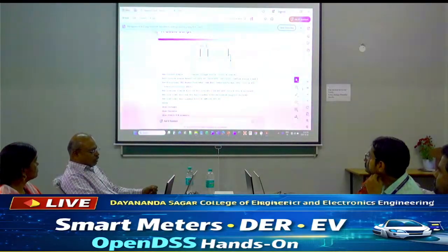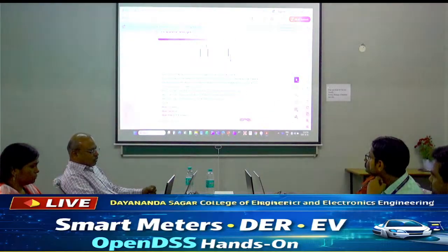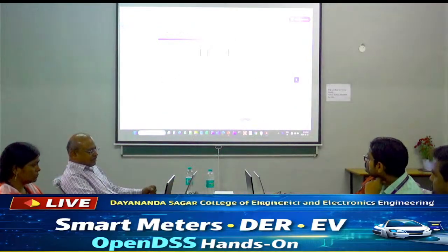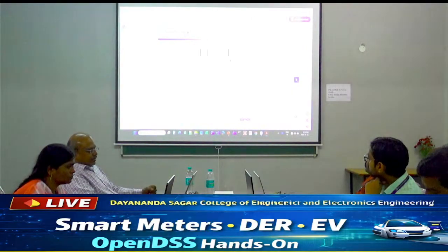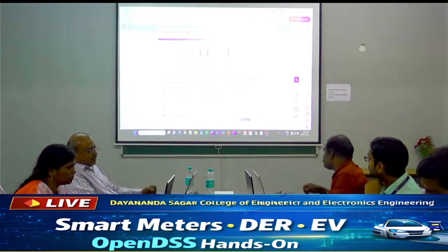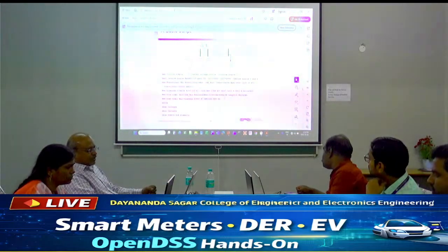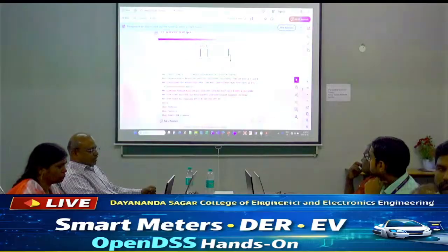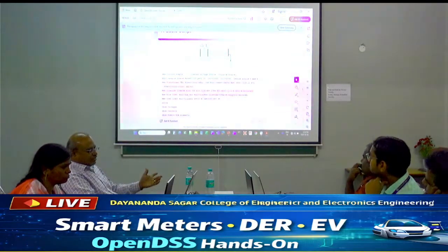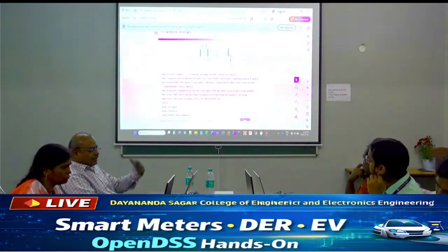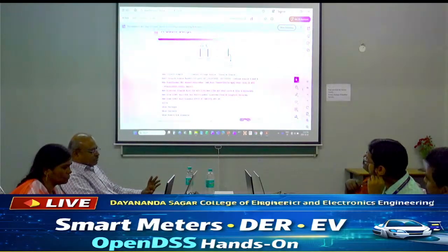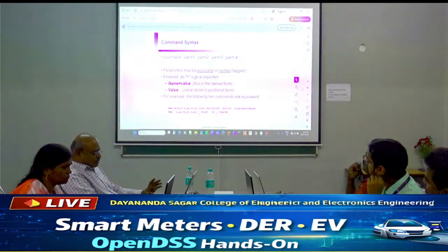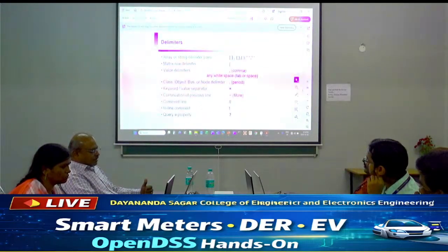And then you define the load. So the load's name is load 1. It is connected to the load bus here. And then it is 12.47 kilovolts and 1000 kilowatts and power factor of 0.95. So once you have put this in, then you can say solve it, and then you can say show voltages, show currents. So it will solve this circuit and it will show. Okay. So this is the basic one, and this tutorial explains everything, like what the syntax is, right,